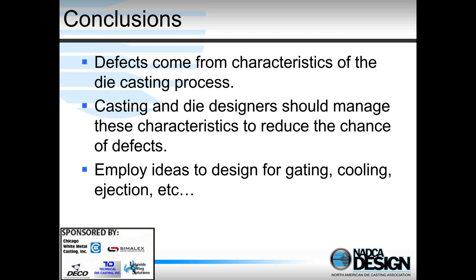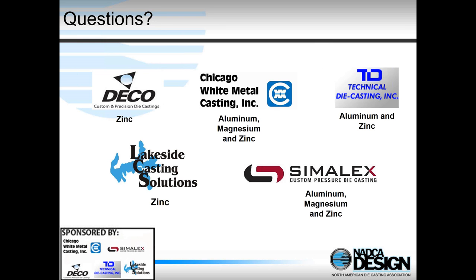And then obviously the idea is to have the discussion early between the various people, the part designer, the casting producer, and probably the die designer too, to talk about how you're going to gate it, how you're going to cool it, how you're going to inject it, where you're going to put various features. And if you can do that and optimize the part design early, it's going to run much better in the die casting process. So that's all we have today.